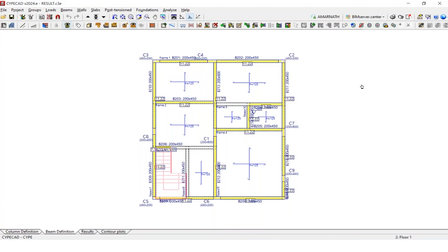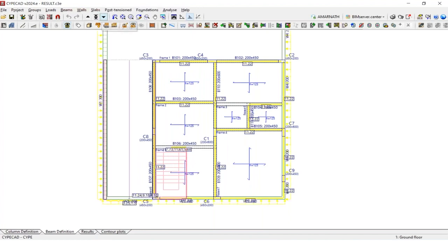Yeah. Probably the shear wall right now, which is using the American code design. If you can apply the Indian code, yes, add the Indian code, that would be better. Number one. And there are many things in the code design, code checks, that are not implemented. For example, for the RC wall, we don't have a code check similar to the column and beam.